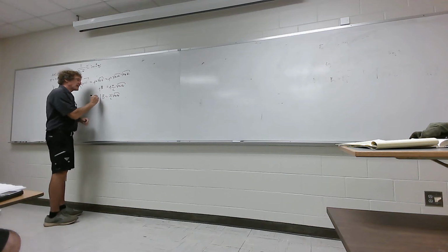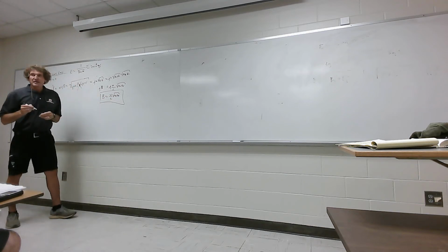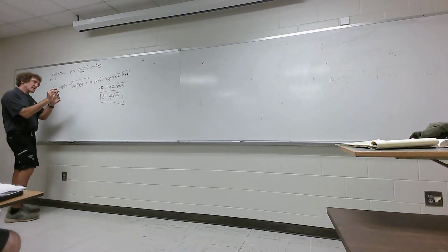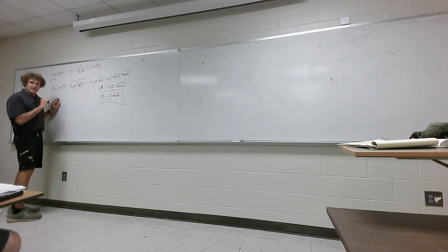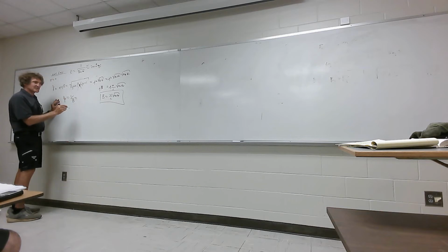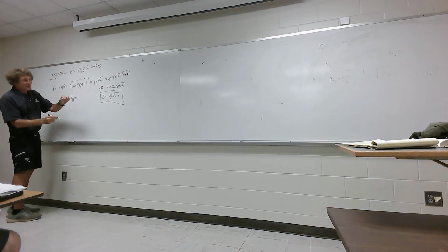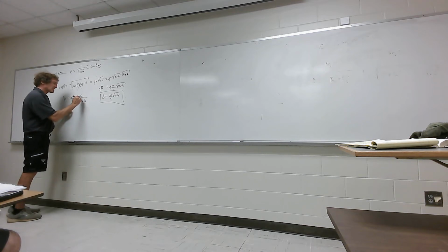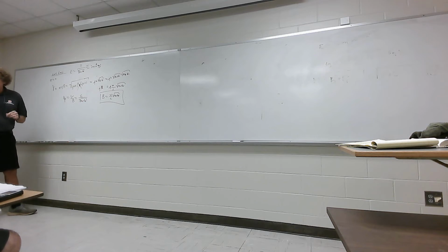Now, if that's beta, how do you get phase velocity? I like to go through it this way. We got beta from the definition, right? From the fundamental definition. What's phase velocity always? Omega over beta. That's right, omega over beta. That's going to be great. So if I take omega over beta, what do you see happening? It becomes c over the square root of mu relative epsilon relative. You all follow me on that, guys?